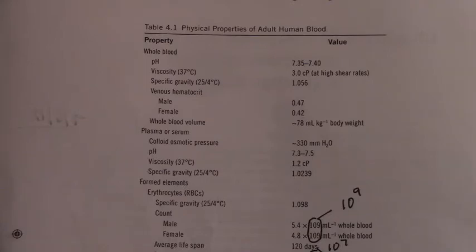If you do it really fast, that's a high shear rate or a high rate of deformation. So deformation is also the change in the velocity, the derivative of the velocity with respect to the direction normal to the deck of cards. Okay, so the shear rate's going to be the velocity in the direction that your hand's moving that's causing the shear. We would call that, say, Vx, and the y direction would be going into the deck of cards. So the shear rate's going to be dVx/dy, which is also the rate of deformation. You might have talked about that when you took biomechanics.